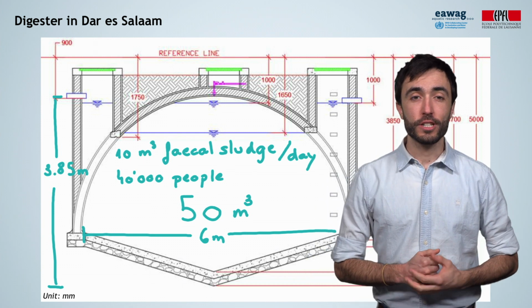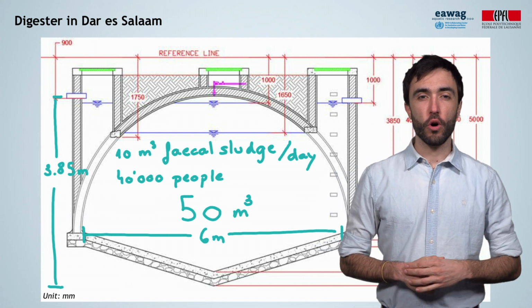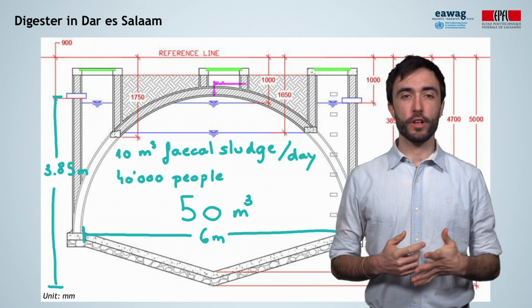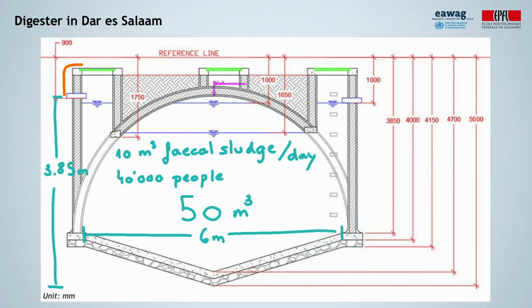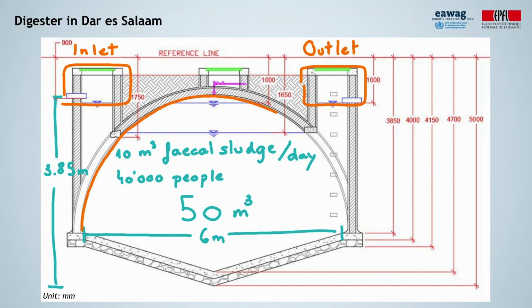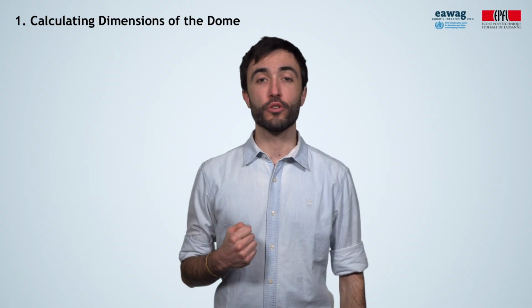Thanks! For those listening to the module, remember that wet mesophilic fixed dome digesters operate in continuous mode as shown in a previous module. We distinguish 4 main important elements: the inlet, where the material comes in, the outlet, where the digestate leaves the digester, the dome, and the gas outlet. Now, let's see how they built each of these components. Let's start with the dome.